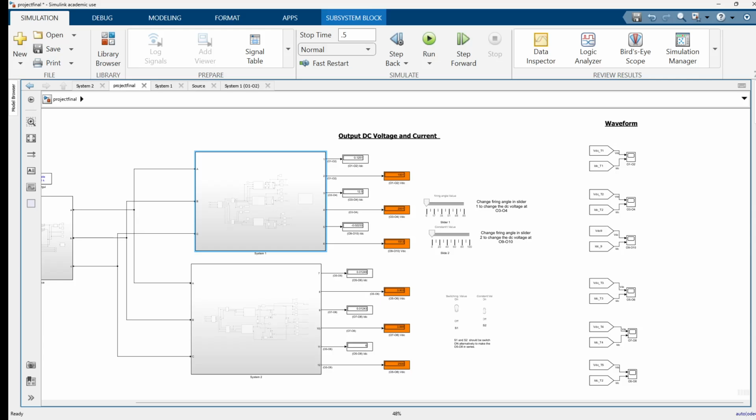So this design highlights an important trade-off in power electronics, where your diode rectifier offers very high efficiency and simplicity, but you can say that this cannot be controlled. Since the diode cannot be controlled, you can't make your output variable.